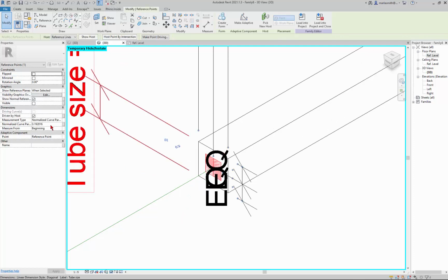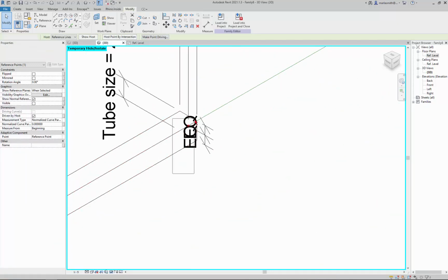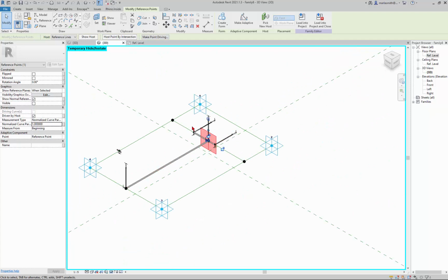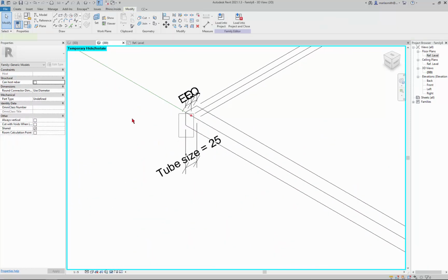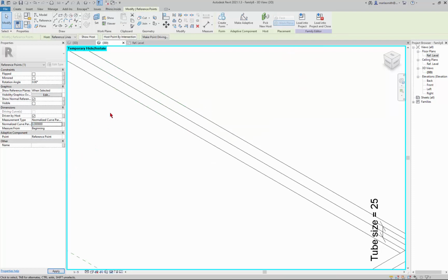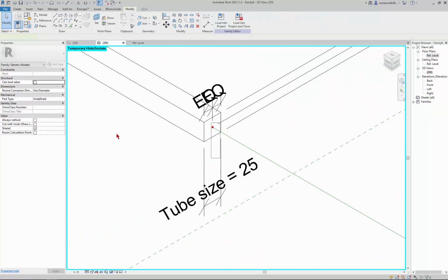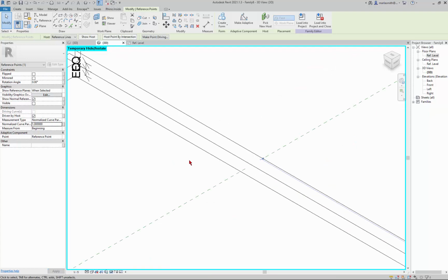And if you get that point, you can set it to 0, and it'll go to the end of that line. Same thing for this one, so I'll come in and window around and get that point, and I'll set that to 1. Right, so it's just going to the end of the line. Same for these guys. So just get the point, however you want to get it, and set that to 0, and then set this one to 1. And I'm not putting parameters on these because they're probably not ever going to change. I don't really need to control them.